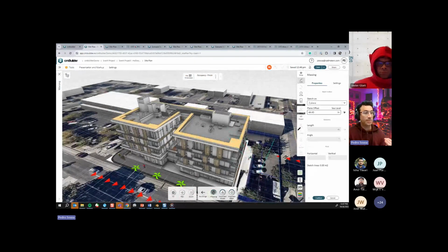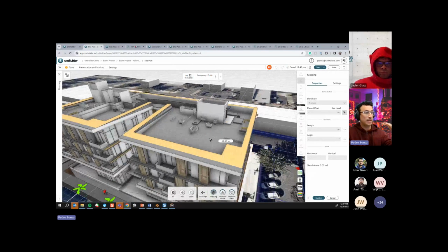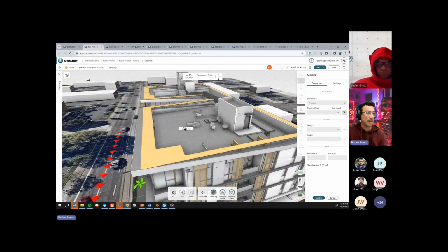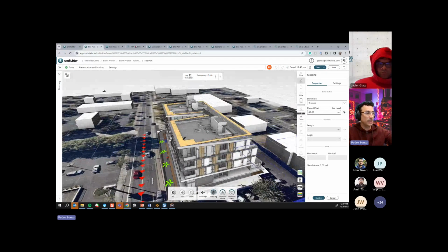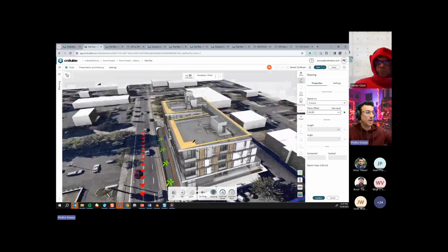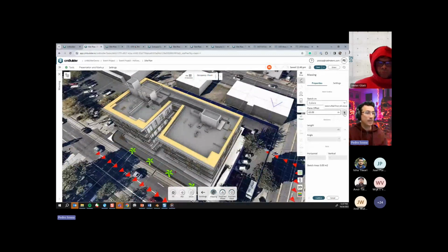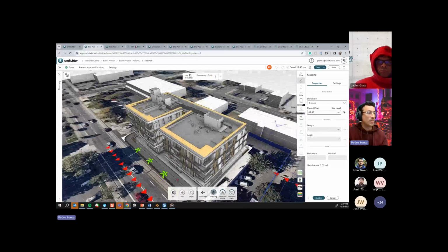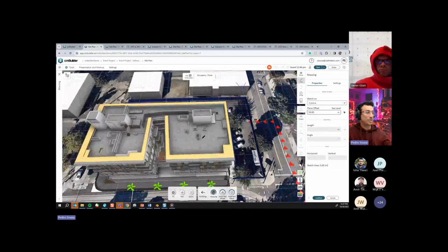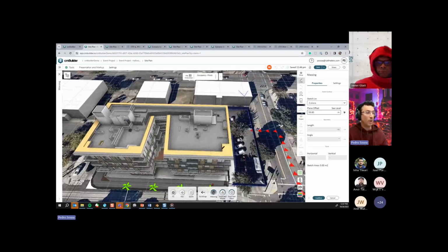And because it's a parapet, I'm going to make my sketch be anchored at this level. So I'm going to click on this button over here and say follow that elevation, right? So now my sketch is positioned on top of that level. Sorry, it's selected the wrong point. There you go. So now that my sketch is positioned on top of that level, what I can do is